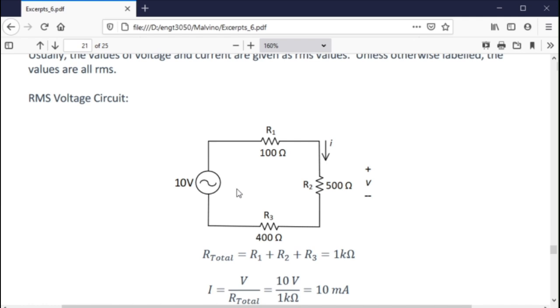So that would be an AC sine wave signal of not peak value of 10, but of RMS value of 10. So it's going to be about 14.14 volts peak for that signal. If I'm looking at it on the oscilloscope, 10 volts RMS would have a value of 14.14 for an AC sine wave. If you're looking at it on the oscilloscope, you would see that.